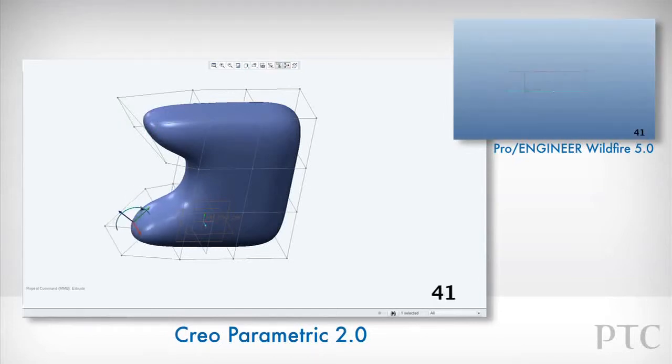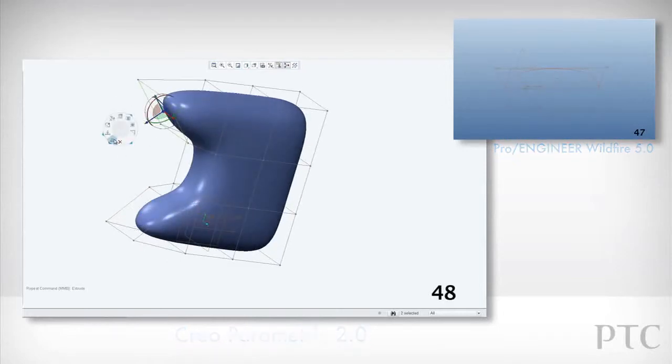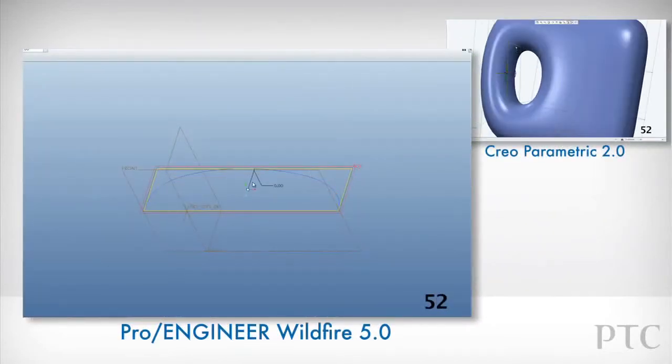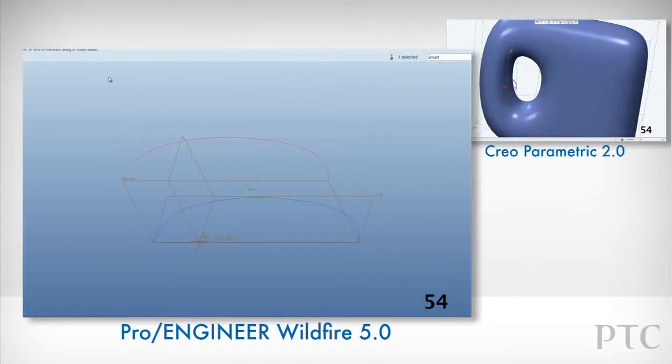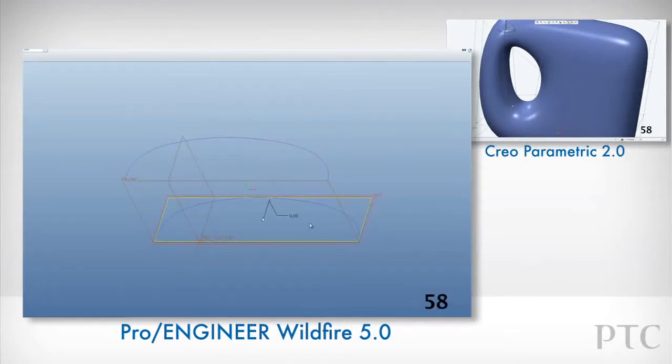Selecting two faces, we can use the Connect command to build the handle for our watering can. And using the draggers, we can make the overall handle thinner as well. In Pro Engineer Wildfire, we would have created individual curves and then blended surfaces between them, having to manually control the connections and tangency as well as between those surfaces.